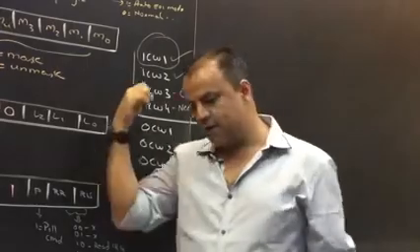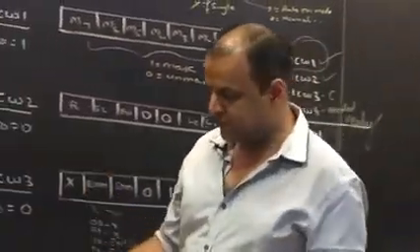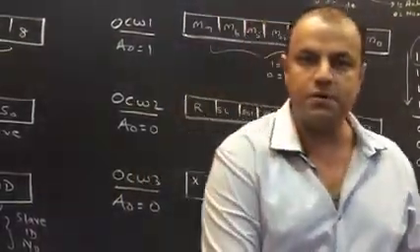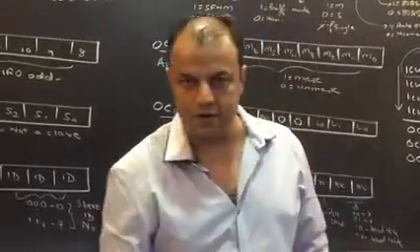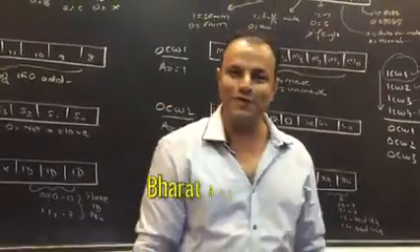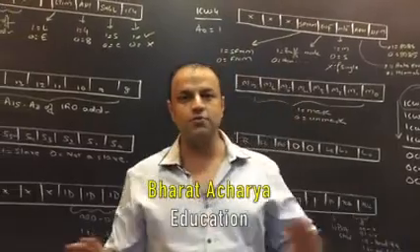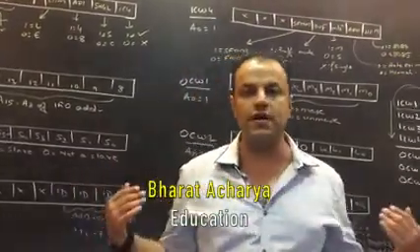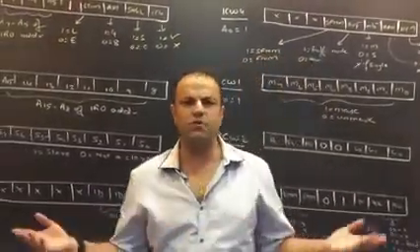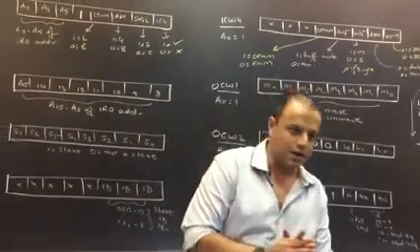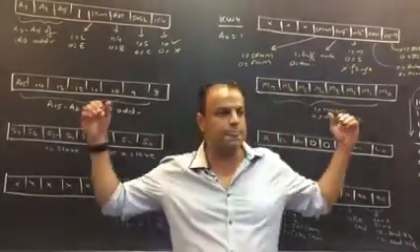Please tell me, did you understand? So just repeat this whole thing for me before we start. ICW 1 and 2 absolutely compulsory, ICW 3 given only if cascaded, and ICW 4 is given only if required. Once you do this, initialization is over. OCWs are our choice. They can be given whenever we want. They may be given in any order, doesn't matter. Now, that was the basic idea.